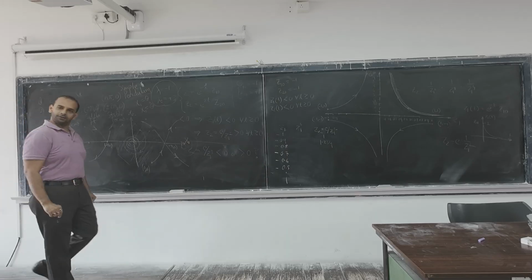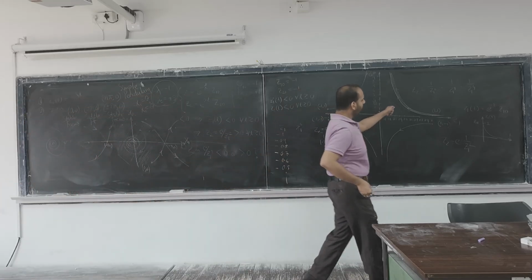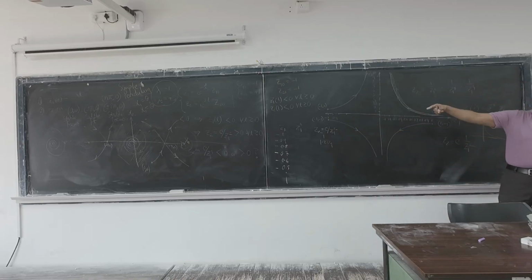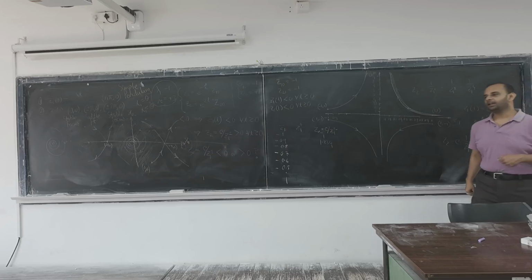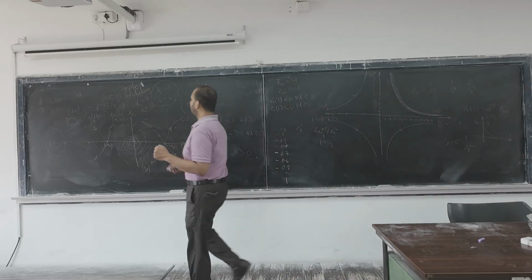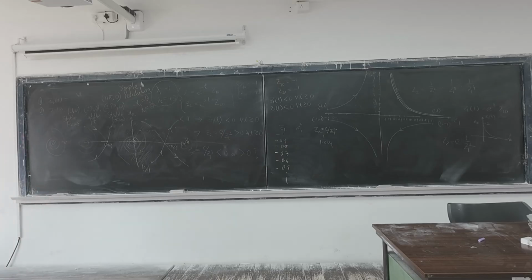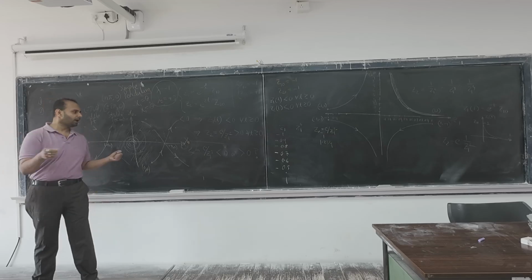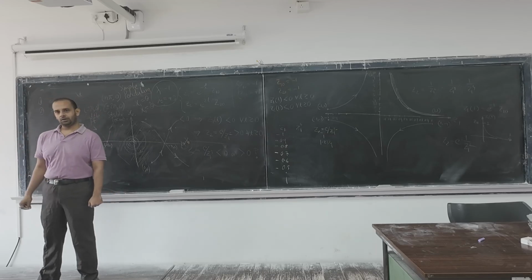So this is about the phase plane analysis, and for that we are doing so much exercise. We are learning it for LTI systems, but ultimately we will have to analyze this. If you see Khalil's book, you will find two case studies. One is the simple pendulum, another one is the tunnel diode. For both of them you will find that there are multiple isolated equilibrium points, and depending upon the region of attraction, or the zone of the initial condition, it would be either a stable equilibrium point or it would be unstable. Okay.